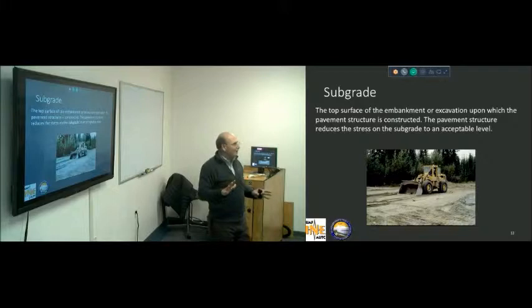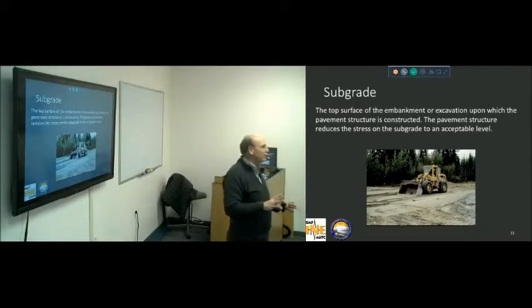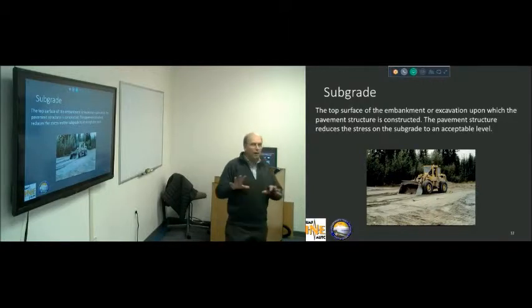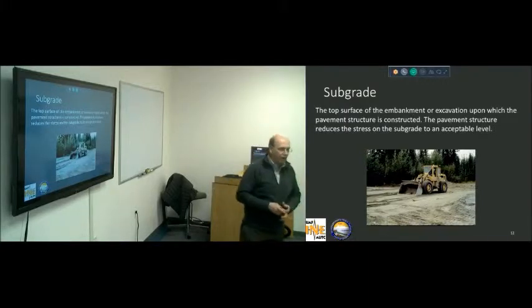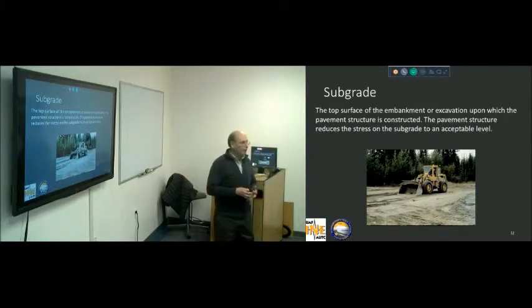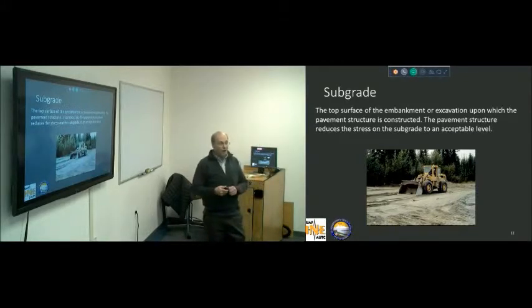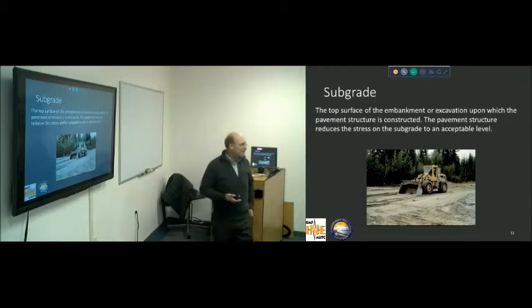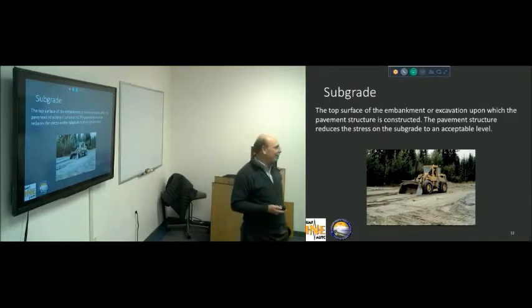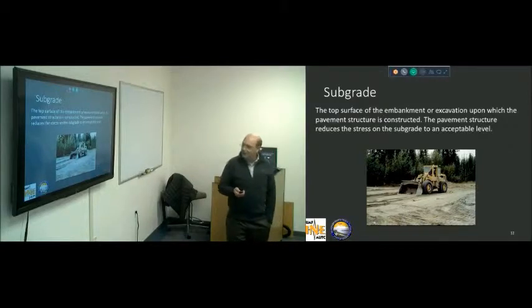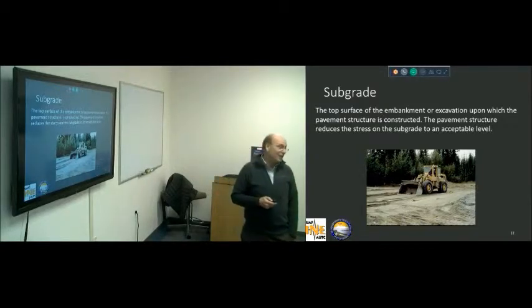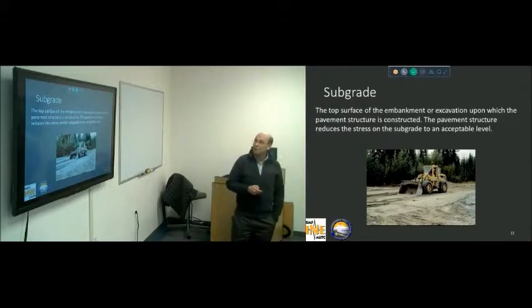That's all a geotechnical investigation. I'm not going to cover that as part of pavement design, but it is part and parcel to pavement design, because we have to assure ourselves that the subgrade can carry the weight of the embankment and the pavement structure, and that's critical that we do that. But that's not part of pavement design. We kind of cast that over to the geotechnical people and said, make sure that that stuff can handle whatever load we're putting on there for the pavement structure, and if it can't, what do we need to do to make it do so? That's a whole different technology or technique that we work on. So I'm not going to address that at all beyond mentioning that that's the case.